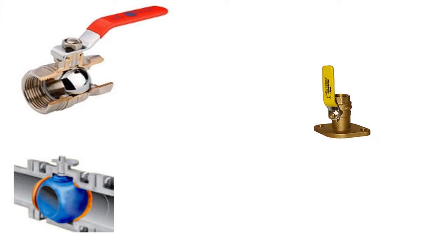Regardless of type, all valves have the following basic parts: the body, the bonnet, the trim, which is actually the internal elements, the actuator, which is a motor that could open and close the valve, or a handle, which can be used to manually open and close the valve. And most valves also have a packing. Packing is used to seal between the handle and the actual body of the valve to prevent water or oil or gas from coming out, depending on what it's being used for.